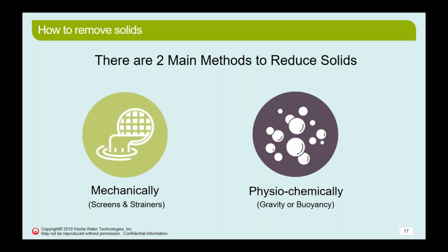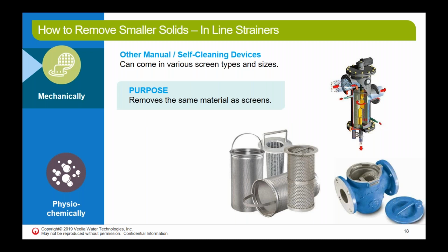Just to organize our discussion, I will be talking about two main approaches to solids separation. The first approach is the mechanical, which only requires mechanical forces to separate the solids. The second is when we're applying physical chemical principles, with the aid of chemistry to separate the solids as well. Obviously, all of them have some mechanical features, but in one case we're talking about gross mechanical separation, and in the second case, we're talking about the addition of chemicals and utilizing the forces of gravity and buoyancy.